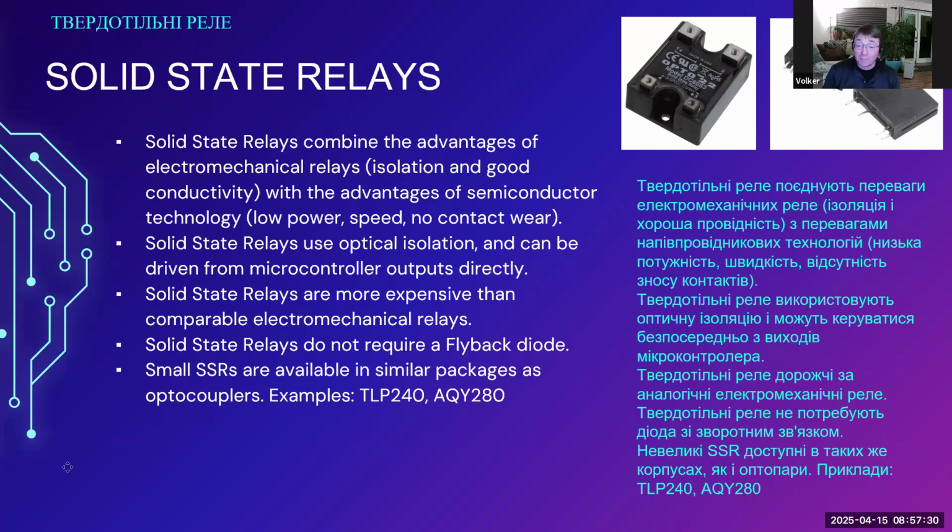Solid state relays do not require a flyback diode. There is no inductor inside a solid state relay. So there's no flyback diode required. It can be switched directly from a microcontroller.